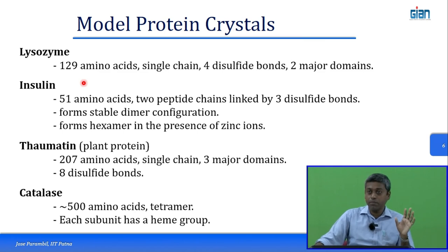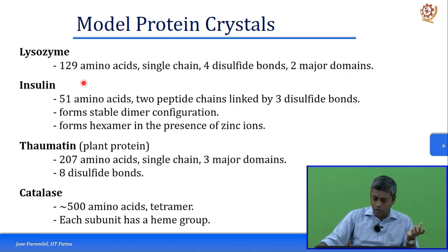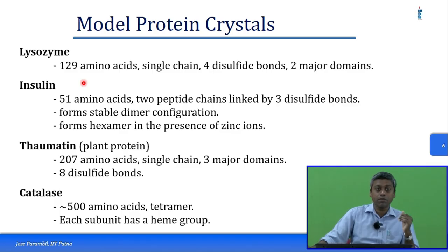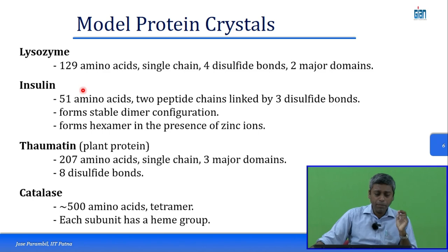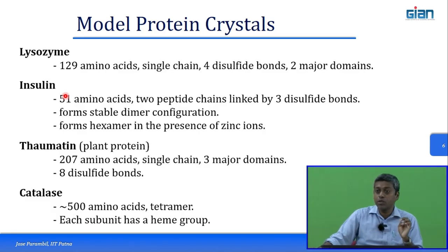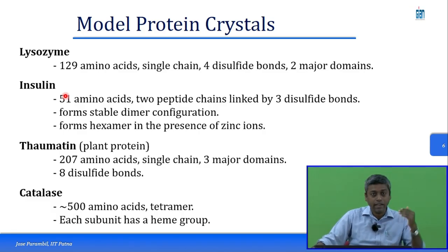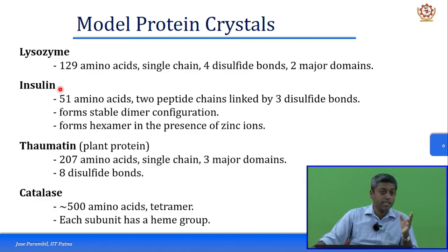But from the process aspect, if you are using chromatography separations for purification, that is typically expensive, because you have to use Protein A chromatography first to get it as pure as possible. Then you have to use the cation exchange and the anion exchange columns to further purify it or remove the other salts and so on. So there are multiple stages of chromatography, which is often quite expensive, especially for newer molecules. But if you can go ahead with crystallization, you can bypass some of those expensive chromatographic methods and go directly into a much purer solid material.